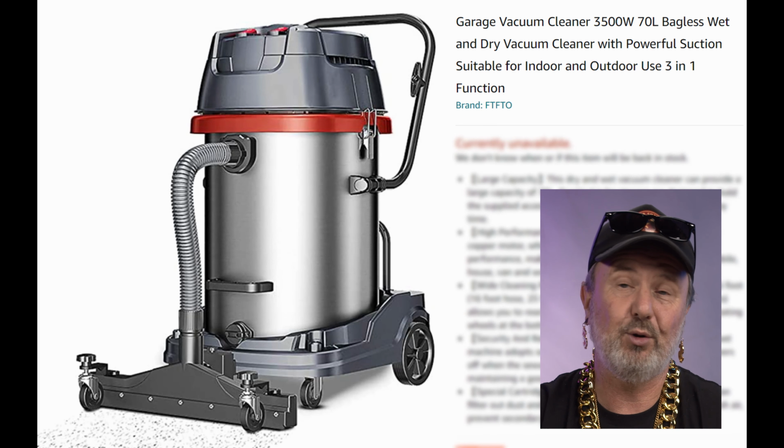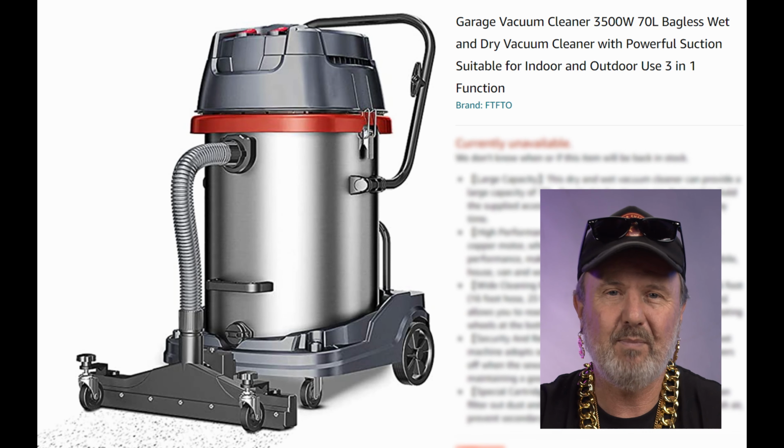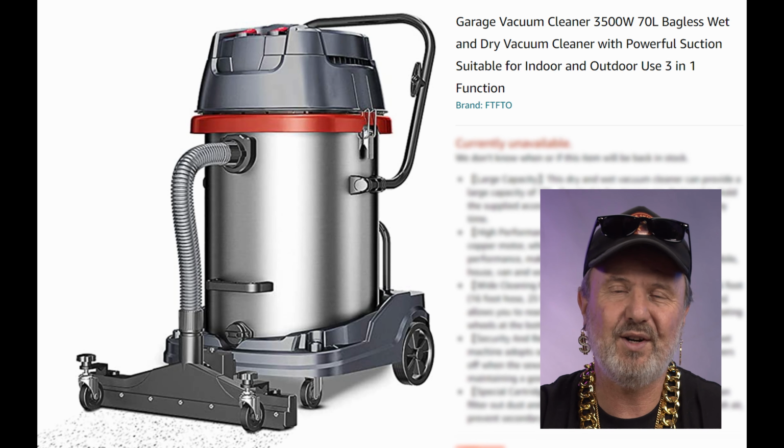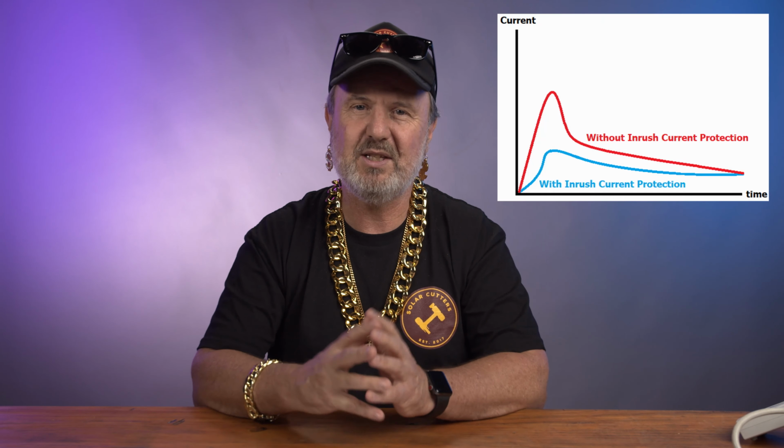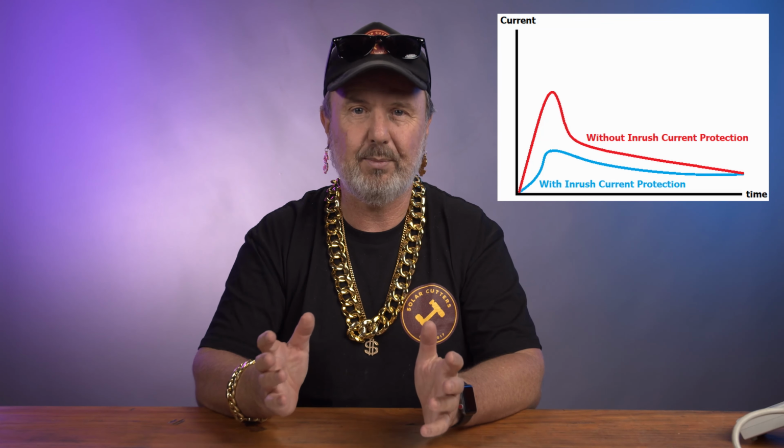I kind of like focusing on the vacuum cleaner these days. Their power ratings are just going insane. It's almost like, apart from cordless ones, mains powered ones have very, very high power ratings. And because of the nature of their motors, some of them is like what's called a squirrel cage motor, they have very high surge ratings. And so you turn them on and there's a wicked amount of inrush. So it could be something like the vacuum cleaner causes the house to trip off.